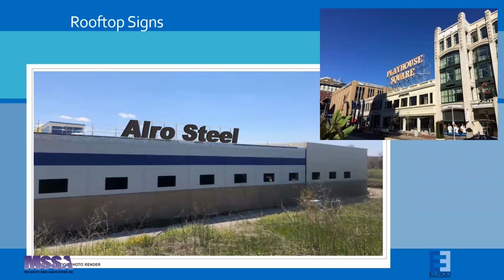Typically, a sign company like a sign engineer like us will limit our analysis to the loads that are applied to the roof. Because the building is just so complicated, we won't try to figure out if the building itself can handle it. You don't want to pay your engineer to analyze the whole structure and how the loads are distributed through it. So it's really important to have the building engineer involved so that they can approve the loading that is applied from the roof mounted sign structure to the roof itself. The sign engineer will be able to design the framing, but to make sure the roof can handle it, you need to make sure the building engineer is involved.